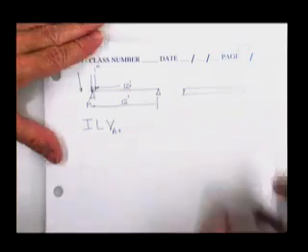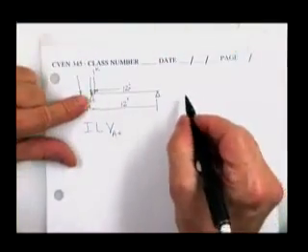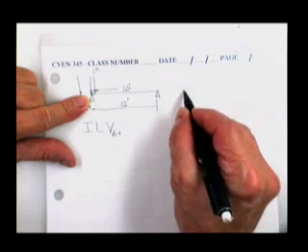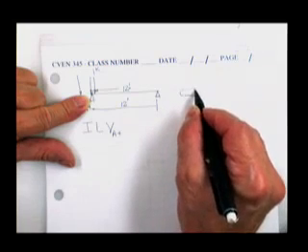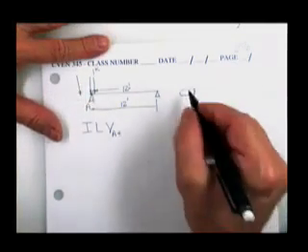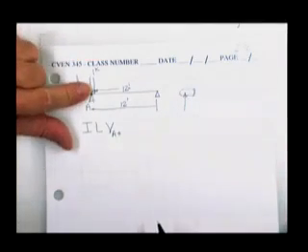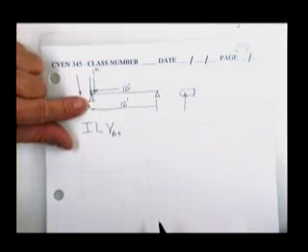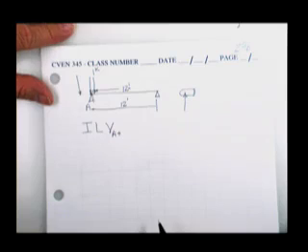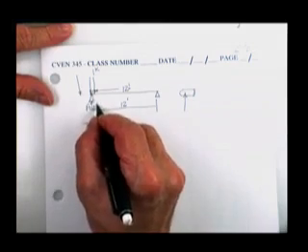Now, let me think about this. Let me draw the other end. It doesn't make any difference which end I draw, but I want to keep on using this same end. There's the beam. I don't even see how you see it. It's so short. Here's the reaction. When you put the 1 kip load on the beam, how much reaction do you cause? 1 kip, correct. 1 kip.